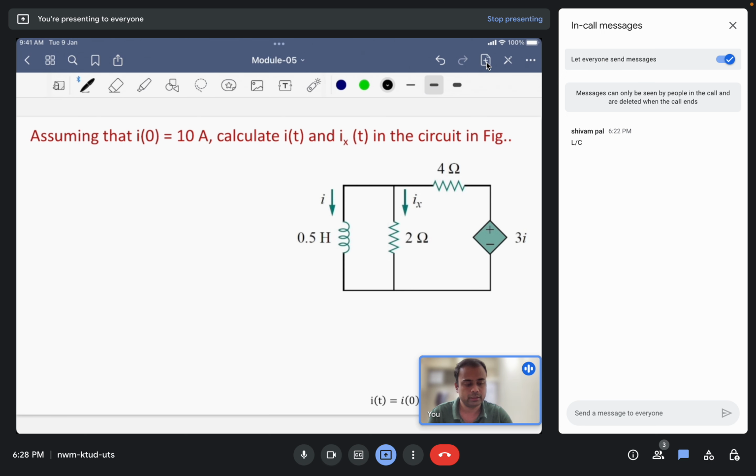To see here, we have a dependent source, that is a dependent voltage source, on the right of the circuit. The rule for a dependent source is that we have to externally excite it with some independent source. So let us remove the inductor here first. I will draw the circuit for this case.